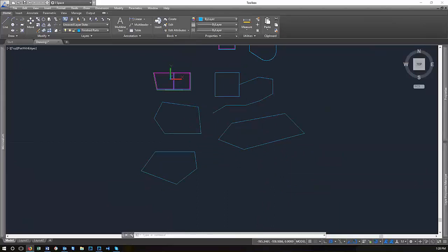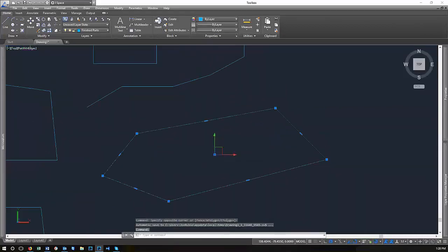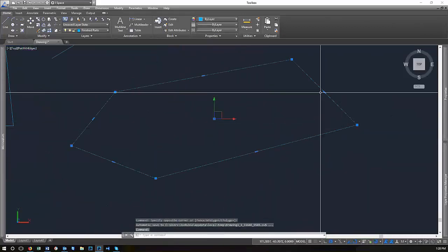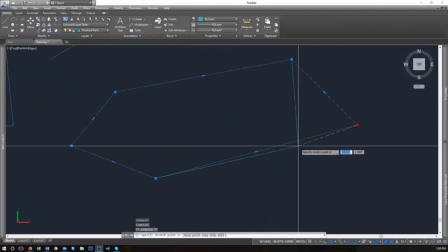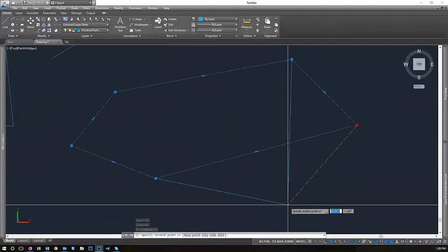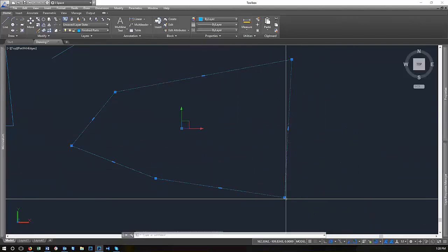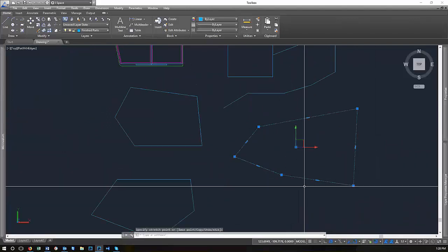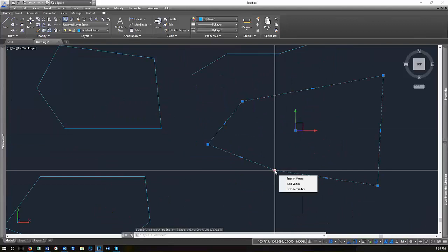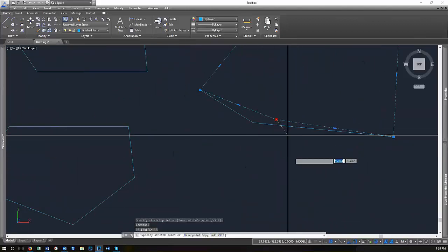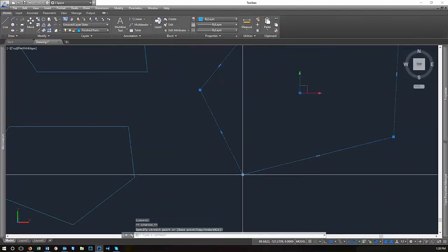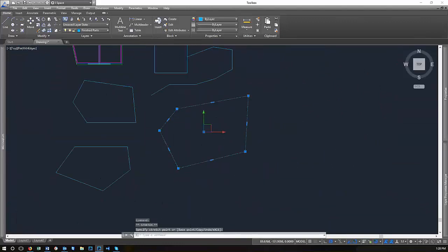We've talked a little bit about grips so far, but if you select a grip, there's a little bit more to talk about. If you select any corner, you can easily move the corner around and it changes your geometry. So you can bring these around and just drop it. It always starts with a stretch command. And so it'll always just be stretching the one point that you've selected. And so that's good to work with.